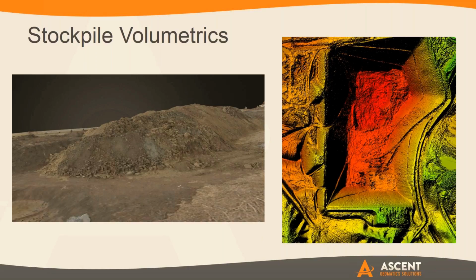When it comes to photogrammetry, you can get absolutes and good relative accuracies. We'll see entire project areas over square miles of land where we'll be at about 0.3 of a foot plus or minus vertically, and horizontally we're right on because we're using ground control. So it's at survey grade two-dimensionally. All of our planimetric features that we can draw in and extract are going to be right at survey grade. Okay, great.